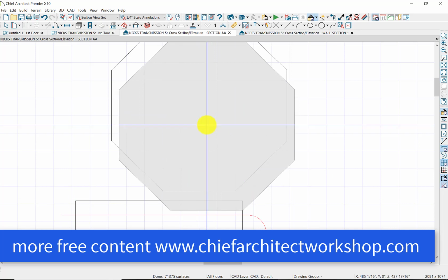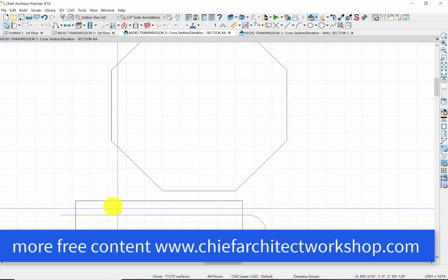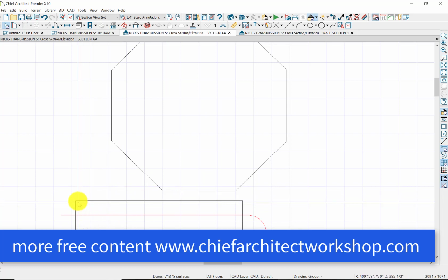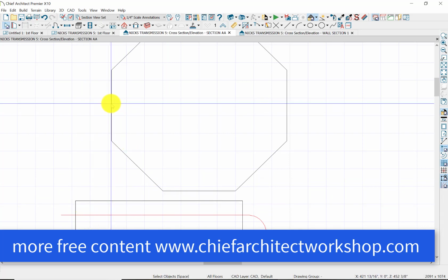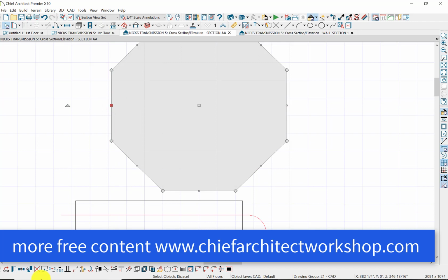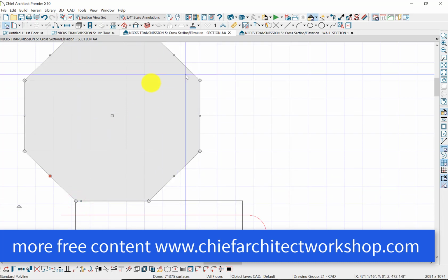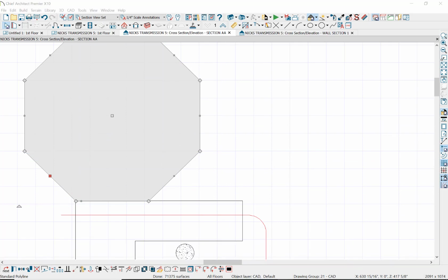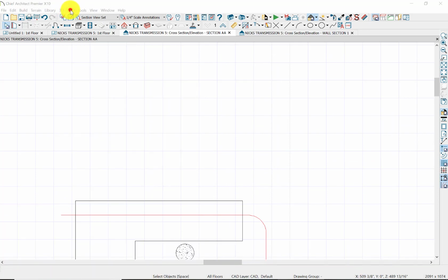Say we have an octagon tower and we want it to go into this corner of the octagon tower. It has to be at this point. That's how we position it. We can grab it, use our point-to-point tool, touch that point, and now we positioned our octagon tower exactly where we want it. All right, now let's move on to the box.